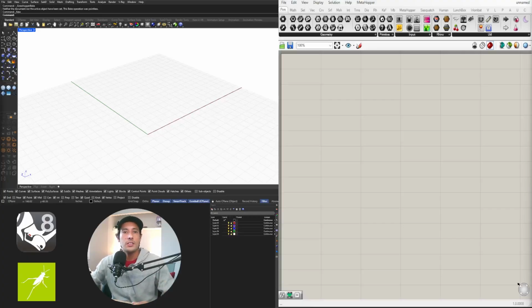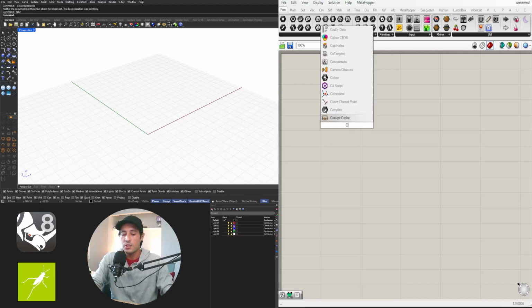All right, so to start the tutorial, the first thing we're going to need is to bring in a point. So we'll go here in Grasshopper. I have a brand new file. The units I'm using are going to be in inches. So what I'll do here is start with the point. I'll bring in a parametric point. Now we can always bring one within Rhino, but let's go here to construct,